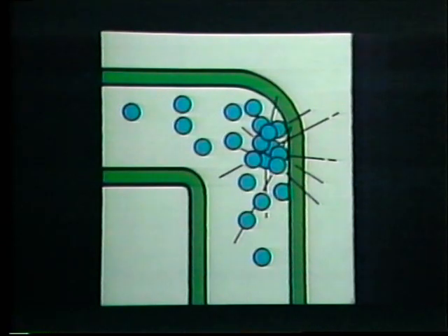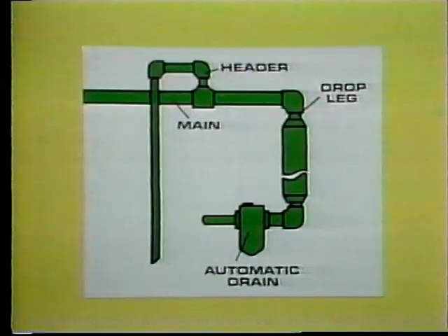Fittings and bends, no matter how well made, add greatly to system friction, and this leads to pressure drops in the line. So if you want to keep the efficiency of the systems you install high, keep the number of unnecessary fittings down.